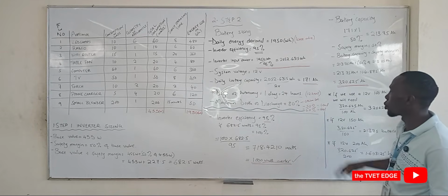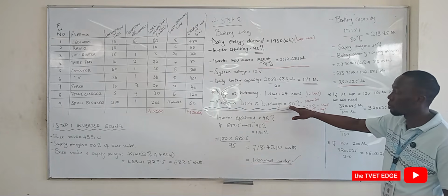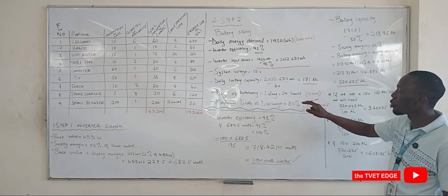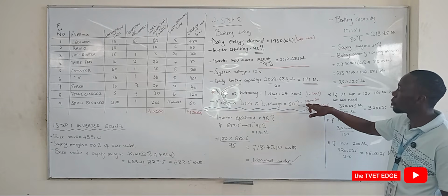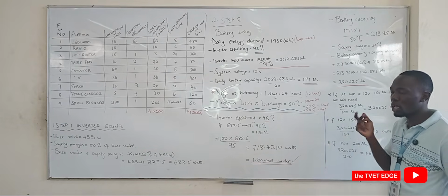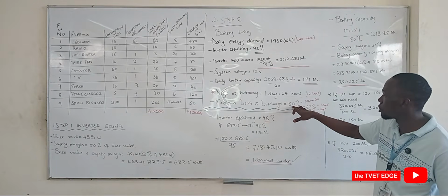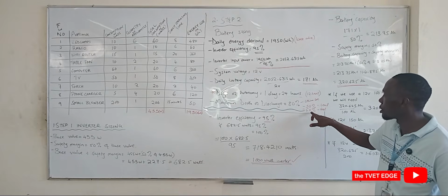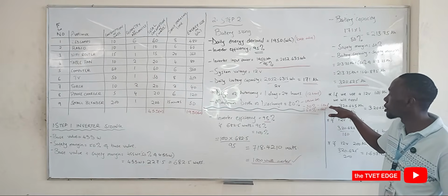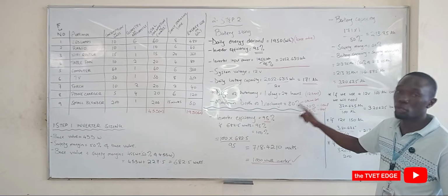So ensure you indicate how you approach these percentages. If you just indicate 80% and don't explain that you are using 80% because you intend to use a lithium ion battery, you might confuse either your invigilator, your examiner or your client. So if you change this value, indicate and say I'm using 60% because I'm going for gel batteries, or the client can afford gel batteries, because the different battery chemistries also affect the financial decision that will be made overall.